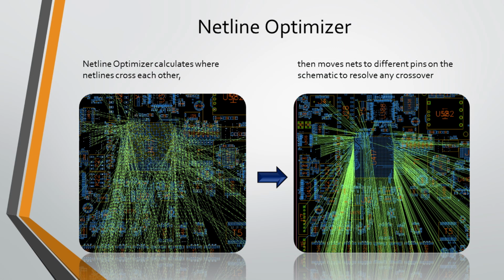Like IO Designer and IO Optimizer, Netline Optimizer uncrosses or unscrambles netlines on components where net pin swapping is permitted. The difference is that it does this with almost no setup, no special symbols, no need for making pins swappable in the part definitions, and no restriction at all on what components it works on. There are only 2 requirements to make it work.